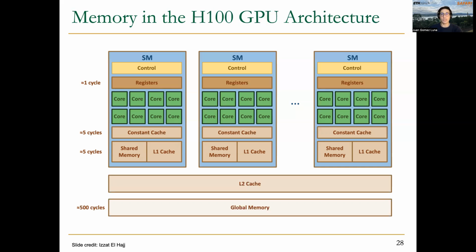As novelties in the H100 GPU, we will see the possibility of doing direct copy from global memory to the shared memory without having to go through the lanes in the GPU cores and the registers. And it will also be possible to communicate directly from SM to SM inside the same thread block cluster.